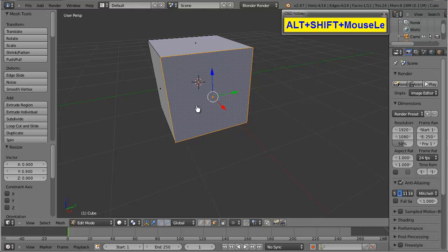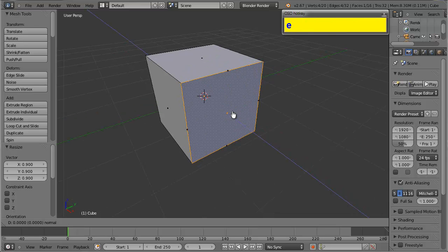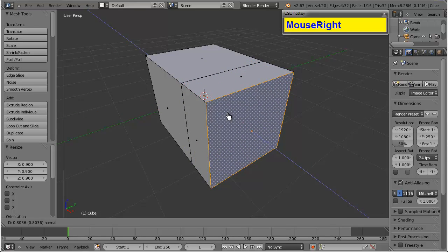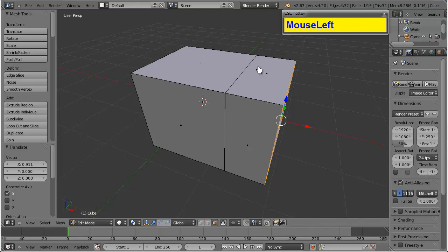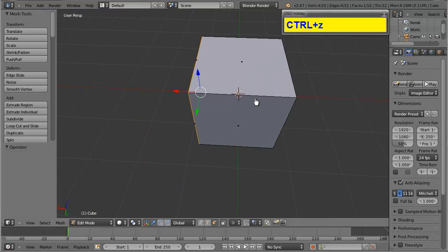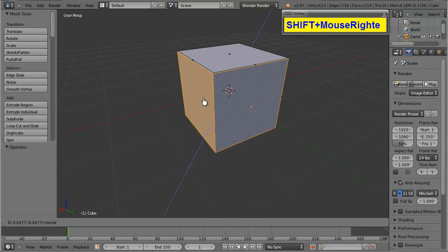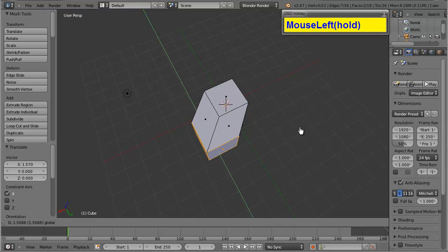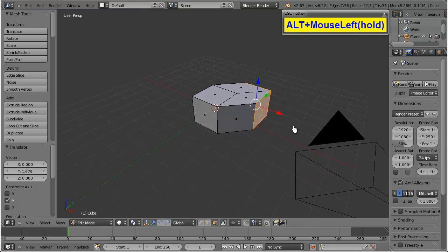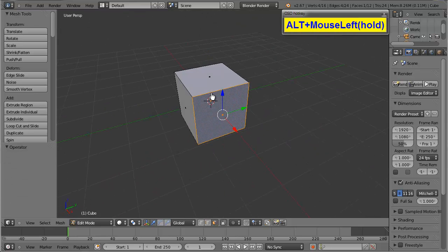Okay, so to make a door, what I'm going to do is select the face, the side where the door is going to be, and press the E key. And what the E key does is extrude whatever I have selected. So if I have this side selected and this side selected, it's going to extrude from both sides. Okay? So I just want to extrude this.